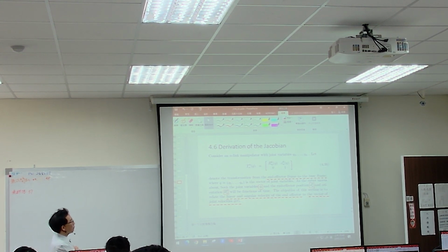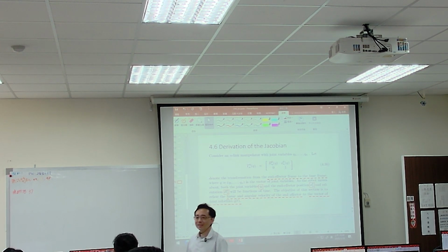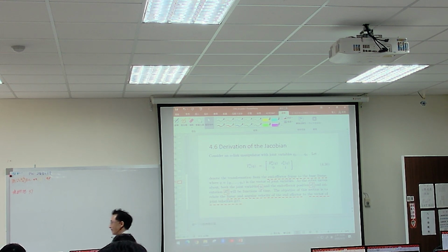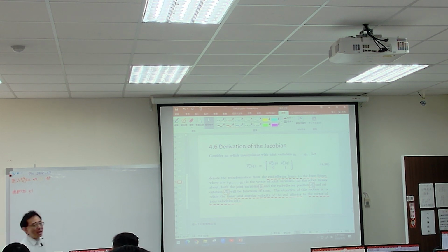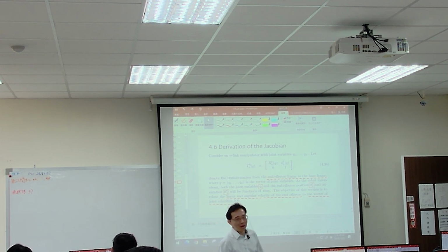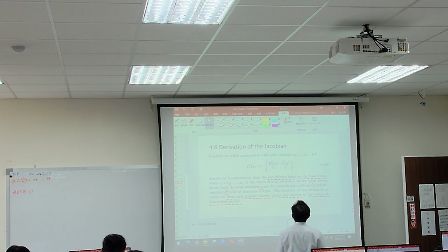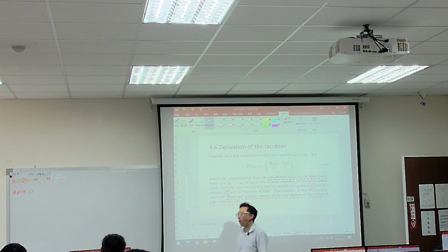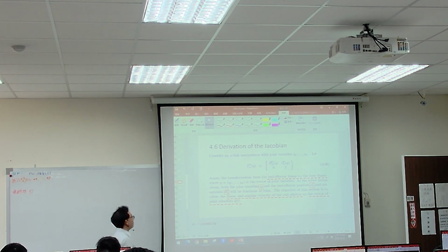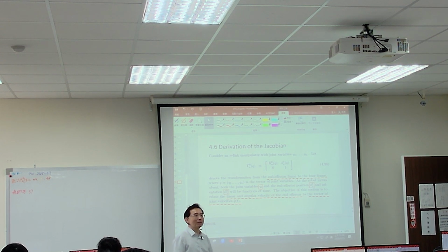Remember, what is the dimension for this one? 3 dimension, we call 3 by 3. No, you did not pay attention too much. It's 4 by 4, it never changed. After chapter 2, every final transformation is 4 by 4. Why? Because the rotation matrix is 3 by 3, right? How about the position matrix? What is the dimension for position?